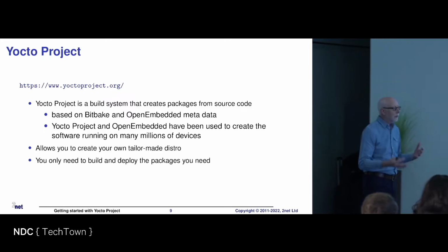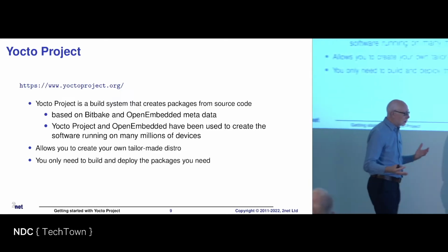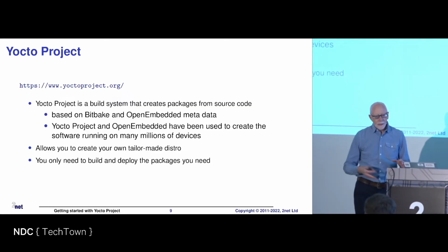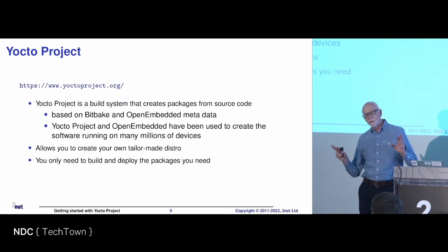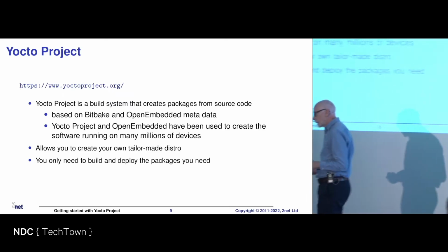So with Yocto, you feed it some rules and specifications of what you want to build, and then you set it building, and then you come back 3 or 4 hours later, hopefully it's done what it had to do, and you now have some images which you can just flash into your system or put into an SD card and boot your target device from.